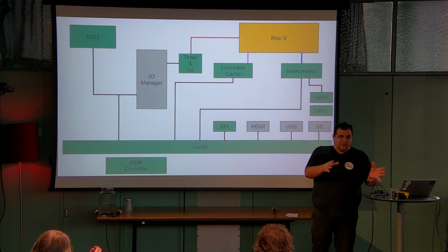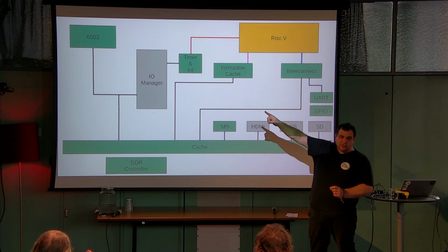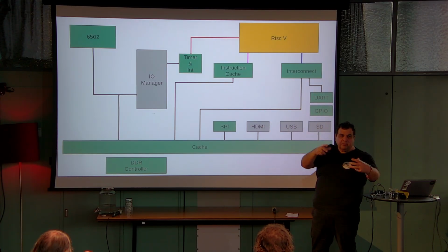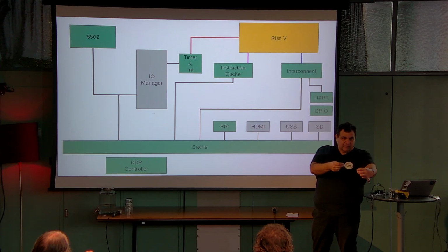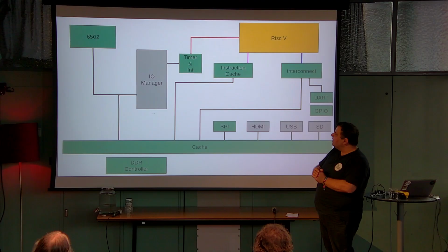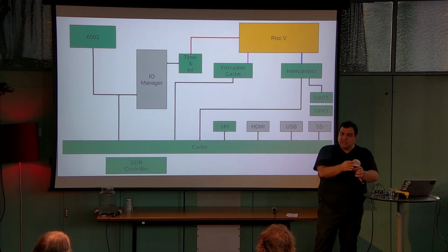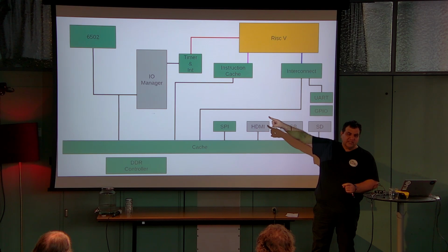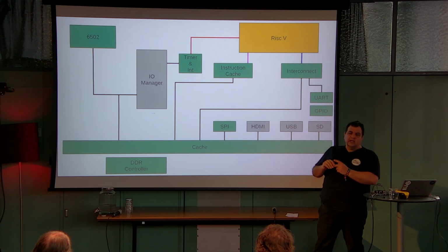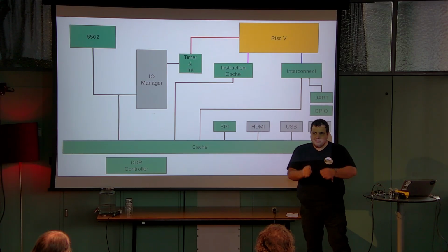It doesn't make it better, it just makes it better for this project, which is I run the 6502 at the same clock speed as the RISC-V and on the same type of bus, so using a synchronous bus, because the original 6502 uses an asynchronous bus. And then I just use the synchronous bus back pressure mechanism to slow it down to the 1 megahertz it needs to run at. And that means fewer clock domains inside the design, and it means that it's a better fit. It's easier to manipulate things.